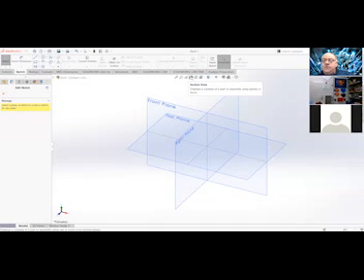There's a section view, so you can cut your model in half, and so you can see if it's hollow inside or if you want to change the nature of that. There's a dynamic and annotated views. So if you like a view and you want to come back to it, you can save it and then name it so you can recover it. We have a view orientation cube, which we'll look at really, really carefully once we get our first model drawn.